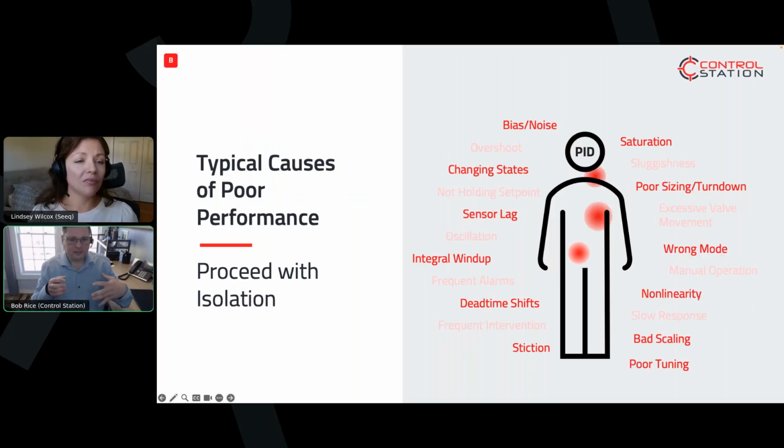Yeah, those PID controllers tend to really be the heart and soul of everything. When things start to oscillate, you get a lot of operator interventions and a lot of focus on it. What are some causes of poor control? There's probably 10 times as many as what's on the screen right here, but we can only fit so many on a slide. When you're talking about poor controller performance, everything can impact it. You could be changing rates, products, or grades, or you could have an operator come in and decide they want to run the process in a completely different manner.